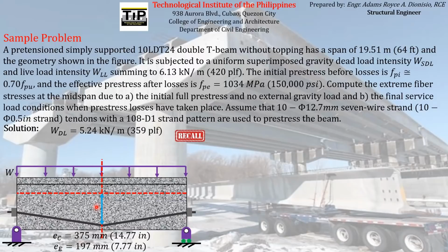In our discussion, the total stress acting at the pre-compressed zone, which is the zone originally experiencing compressive stresses as the concrete element supports its own weight, which is in this case the upper portion of the concrete above the neutral axis, or in general the upper portion of the concrete element. So that is the pre-compressed zone.